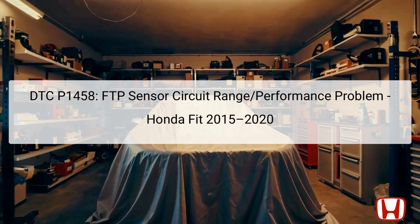The Diagnostic Trouble Code, DTC P1458, indicates a problem related to the fuel tank pressure, FTP sensor circuit. This component plays a critical role in monitoring changes in pressure within the fuel tank and can influence the vehicle's emissions control system. Located on the fuel tank, the FTP sensor transmits pressure data to the Powertrain Control Module, PCM, for analysis. A fault in this circuit can lead to performance issues, increased emissions, and potential driving complications.